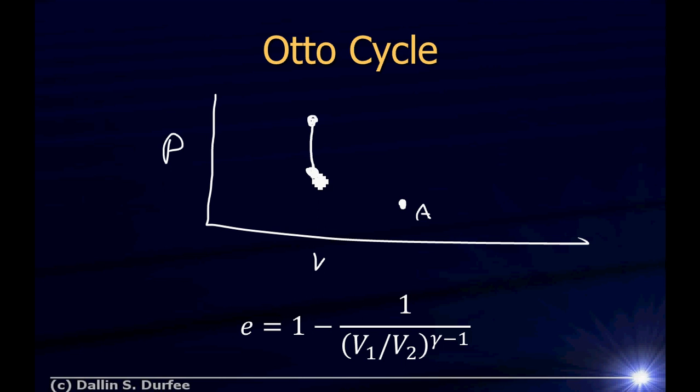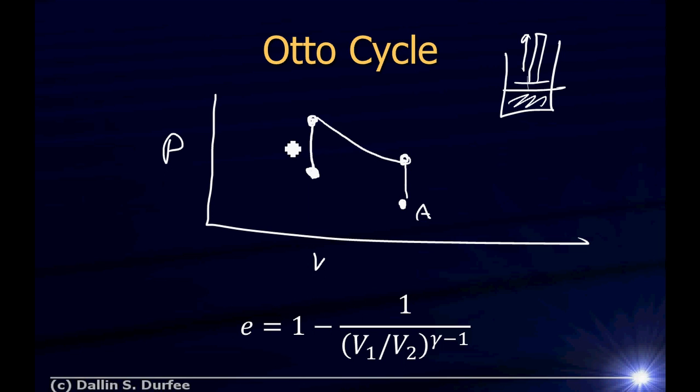Now this gas goes off, so here's my piston. I put in all this heat, and then that pushes upward, and it expands adiabatically. This is known as the power stroke. It's doing work on your drivetrain. But once it expands to its maximum height, it's cooled down, and what we're going to do is now let heat out. So here's Q hot coming in. We're going to let heat come out. We're going to put it in contact with a cold reservoir and get our gas back to room temperature.